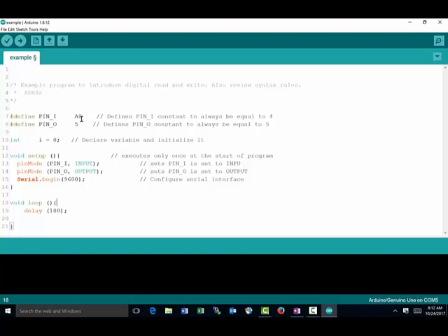Now remember from the previous one, we just had these output pins and input pins. I'm only going to use output pin 5, and when we go back, you'll see output pin 5 has a squiggly on it, which indicates it is capable of doing PWM. Not all pins are capable of doing PWM. I left the other pin in, although I don't need it, so I can keep using the same piece of software to demonstrate different things.